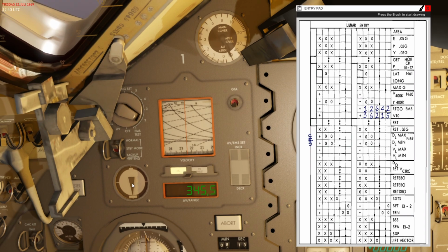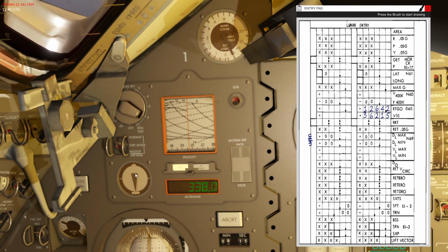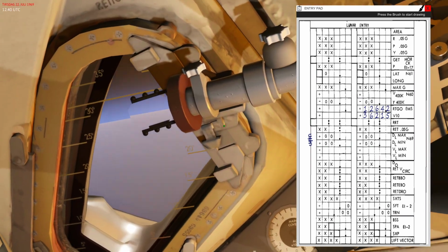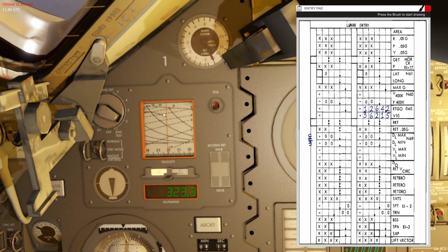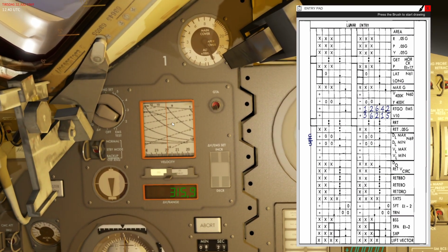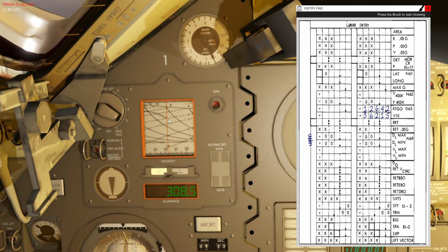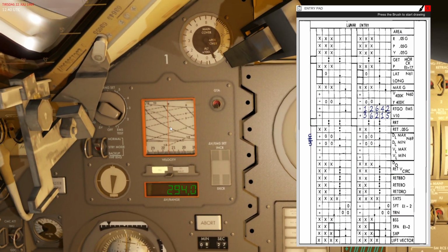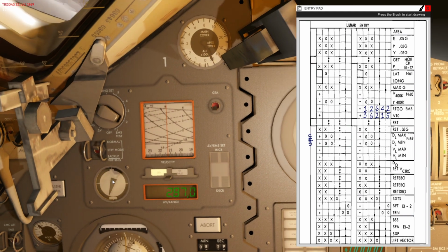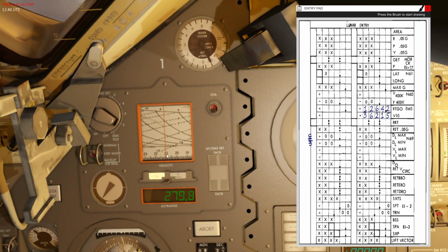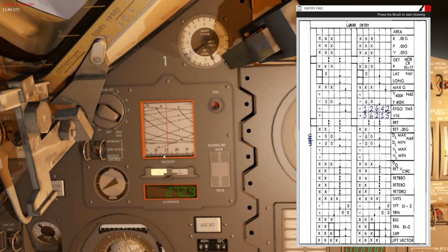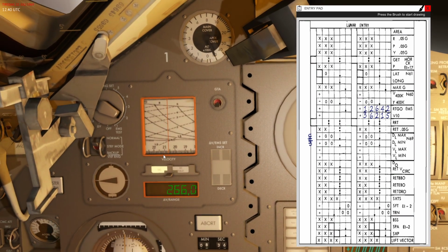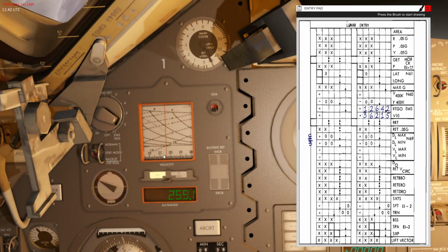Now I'm diving straight back into the atmosphere with my lift vector pointing directly down. This means that I'm now rapidly moving down into the denser part of the atmosphere, and it's very important to be very careful about your lift vector here, because you don't have that much energy left to correct the steepness of your trajectory through the atmosphere.